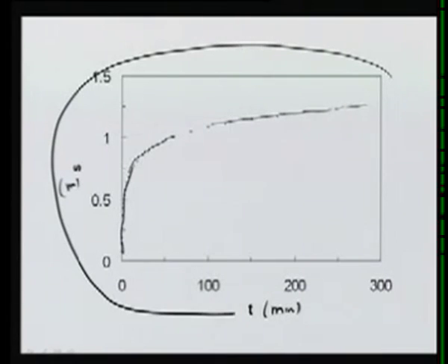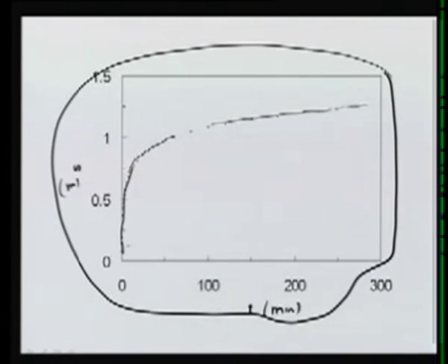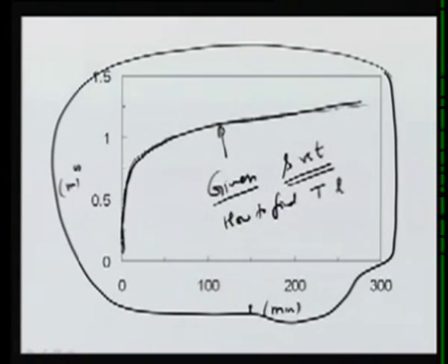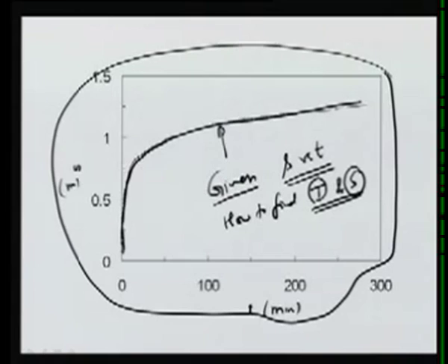So the second question which comes to the mind is, if this curve is given to us, given S versus T curve, how to find T and S? So this is an inverse problem or a parameter estimation problem, in which from a given drawdown data we want to estimate the transmissivity and the storage coefficient.